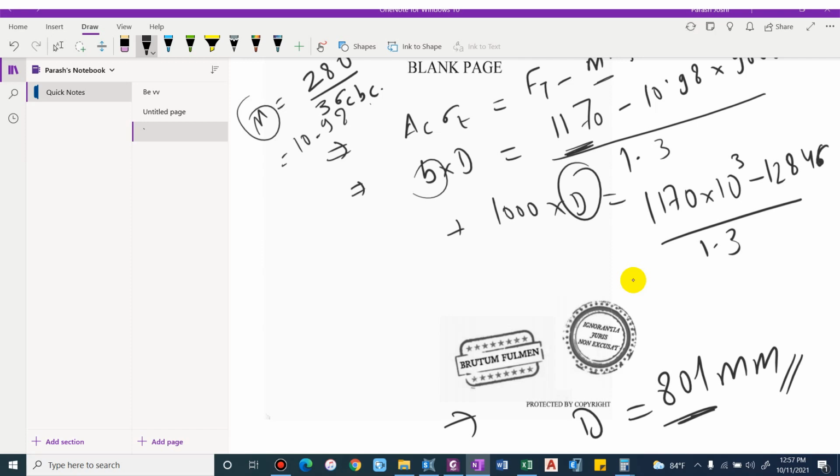For now let us assume the depth to be equal to 1000 mm at base, considering other stresses as well. This is for hoop tension only, so there will be other stresses. To make sure that there won't be any other failures, we'll provide the depth as 1000 mm at base.